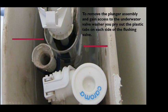Really old systems used to have a ball cock in them, really noisy. The new ones, the flushing valves are pretty quiet. I don't know if anyone bothers maintaining the flushing valves now. It's not really worth it, because although you can buy the washer for probably $2 for most of them and replace it, and it probably will fix the problem, if it didn't fix it and you get a call back, you've just lost all the money you made on the job doing the charge out call out in the first place.